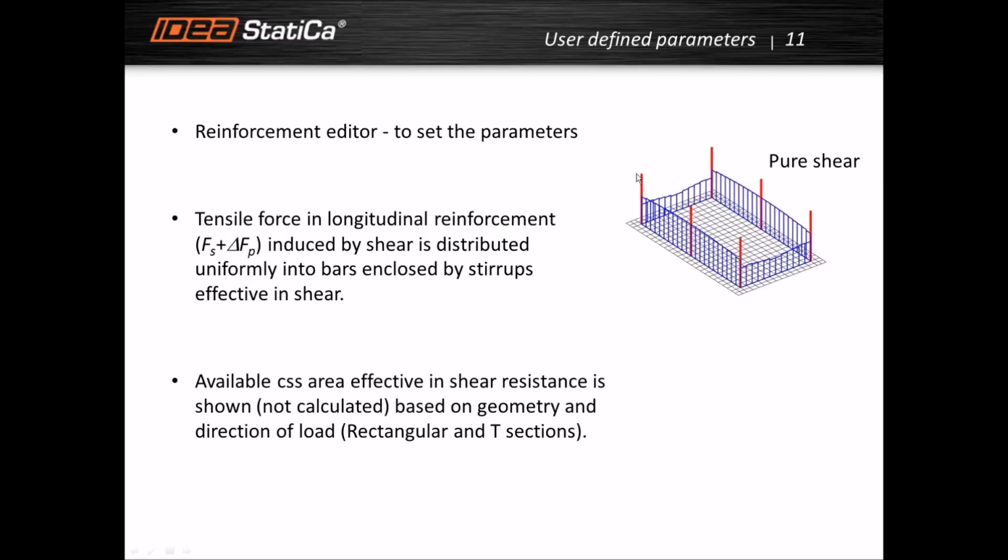And you can see the results. These red lines are the forces in longitudinal reinforcement. Actually, there was a longitudinal reinforcement in the middle of the section, and you can see that this alternative calculation numerical model showed and confirmed our assumption that we have the longitudinal reinforcement loaded, I would say, almost uniformly.